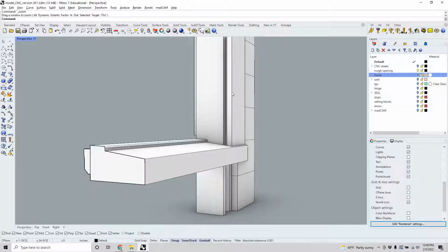As you can imagine, if water gets back in there, which it inevitably does, the stops not only stop the window, but they also stop the water from escaping. And so the water would sit on the sill and essentially start to rot away the wood. So the first thing I did was to remove all those and reprep and get that sill ready to accept a new window.